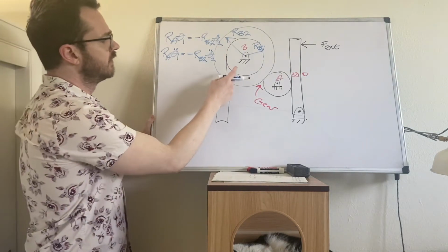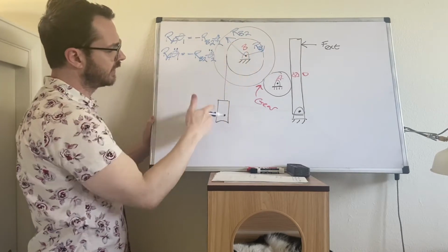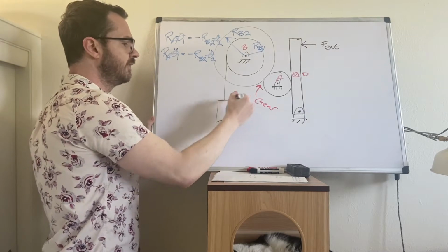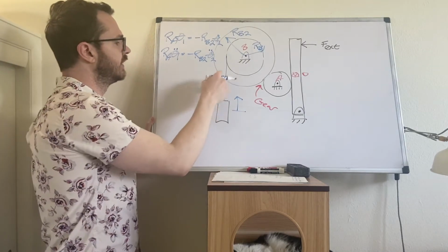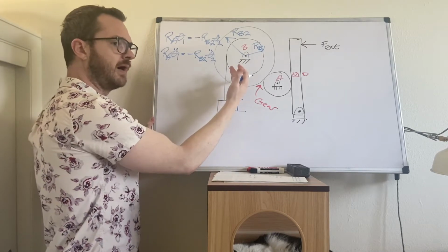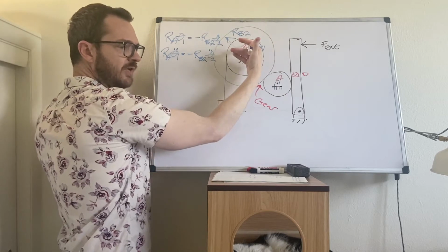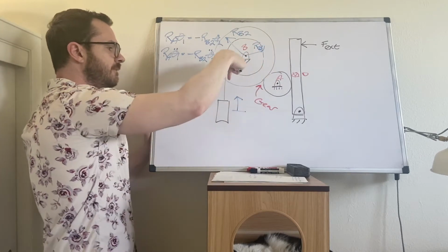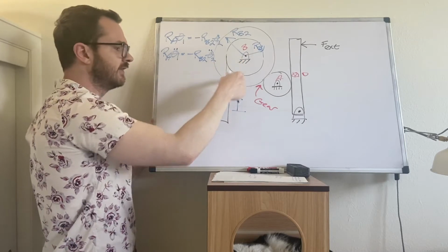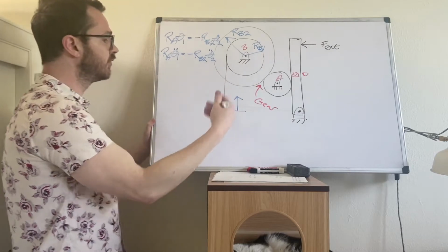Next, constraint for the arc length. As this disk rotates, the block is going to translate. Consider how we defined the position, or how we define the acceleration of the block. We said that Q is positive up. So when disk B rotates in a positive direction, the block is going to drop. So the relationship between the rotation of the disk, the angle theta, and the translation Q is going to be negative.